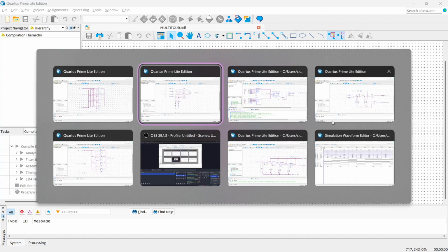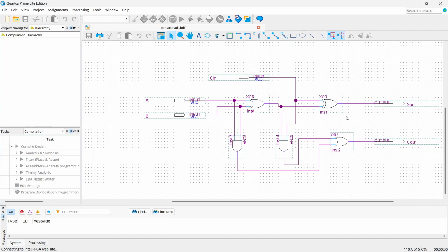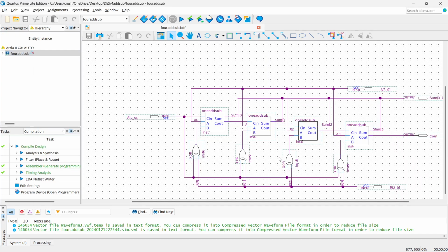So, and then we have for the adders, this is the basic, the fundamentals of the full adder. This is all equivalent to one full adder. We have the C in and we have A and B, the 2 digits, and then we represent it as blocks, and we can combine it to become a 4-bit full adder subtractor. So each of these blocks here is equivalent to the logic gate circuit that I've shown you. We have the ALU operation, which will determine whether it's subtraction or addition, in which 1 will function as subtractor and 0 is addition.